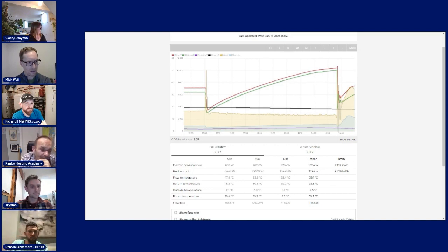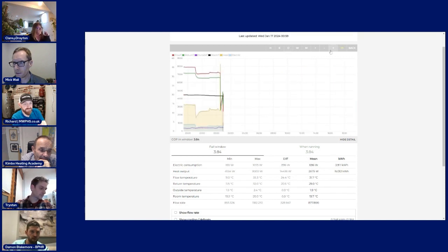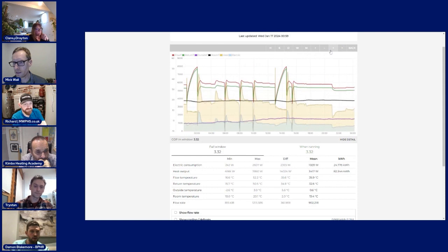All IMI Eclipse valves on all radiators, but we were struggling with a couple of rooms that we just couldn't get the flow right on, to get correct room temperatures. So we looked at it, and because I use the high flow valves as well for the ones needing over 150 litres per hour, we took them out and put the flushing inserts in. All of a sudden we saw the flow rate improve through the unit, and the COP went up, not much, by 0.3 or 0.4 I think, but it improved as a unit. Radiators were feeling a lot warmer throughout. Room temperatures were better.